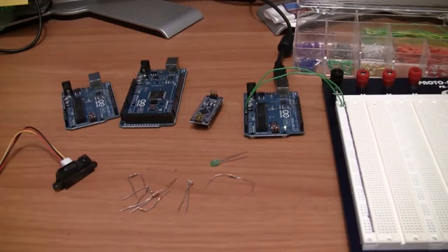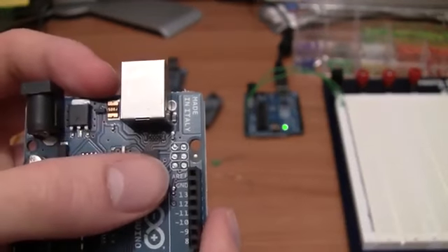You can set the reference voltage that you use for the analog inputs on all these Arduino boards. By default, it's set to 5 volts, or 3.3 volts on 3.3 volt Arduino boards, but here we'll just be working with the default 5 volt boards. You can also set it to an internal 1.1 volt reference, although that's not available on the Mega. And on the Mega, you can use different commands, set it to 1.1 volts or 2.56 volts as a reference. You can also set your own voltage reference by setting it to an external value, which you input into an analog pin on the Arduino. Here we can see the analog reference pin that I was talking about.